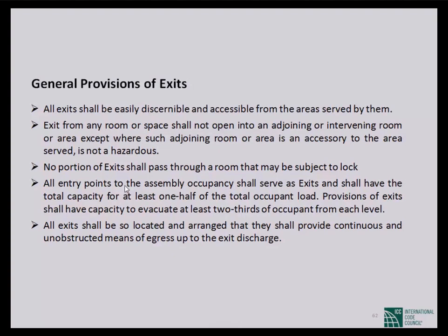No portion of the exit shall pass through a room that may be subject to lock. This has happened particularly in institutions. You must be careful while designing this exit so that it does not pass through a room, and it should not be locked.